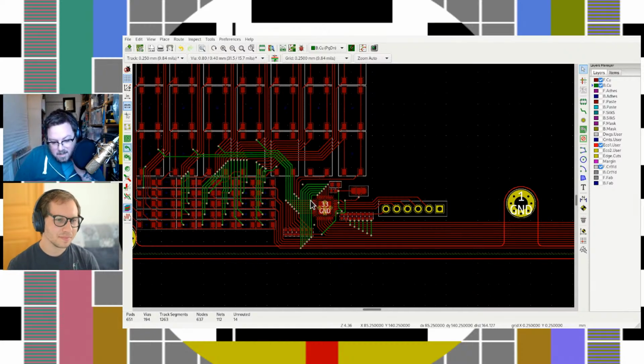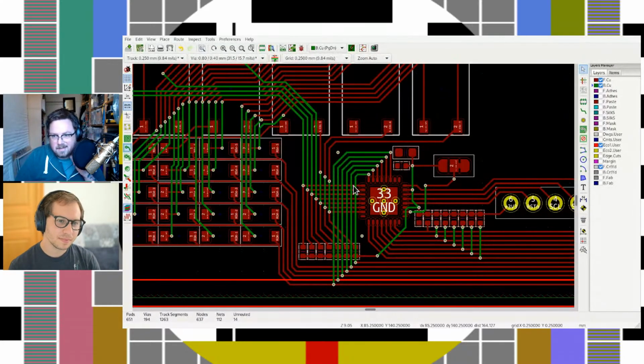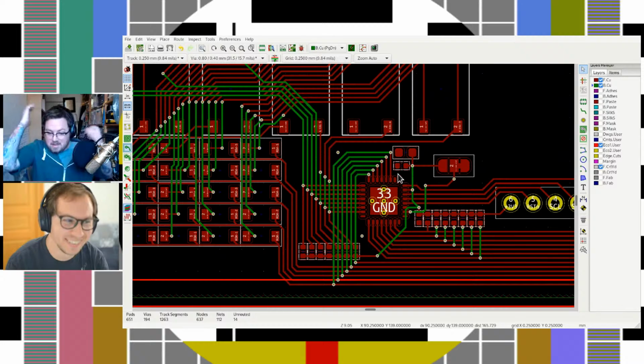So if you can keep your circuit simple and do 2 layers, you can choose some fancier options, and sometimes it's cheaper. And then it's also important to know that circuit board assembly has gotten really cheap, and you can order 4-layer boards for like $20 more. So sometimes, if it would be a huge headache to route something in 2 layers, treat yourself. Spend the extra $10. Get 4 layers. Then you can make the wires go anywhere.